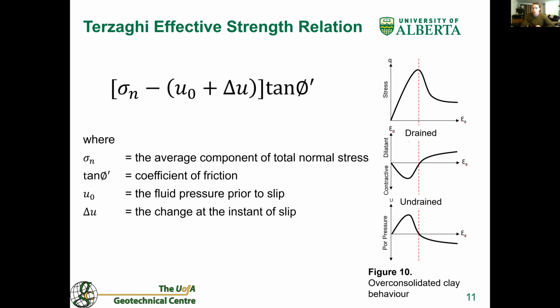It is already well understood that the pore pressure in heavily overconsolidated clays or shales will respond differently when testing occurs parallel or perpendicular to the bedding plane direction. However, there hasn't been definitive evidence proving or disproving the presence of shear-induced pore pressures in a lab setting along either shear bands or along bedding planes, as all testing is currently completed using global pore pressure measurements.